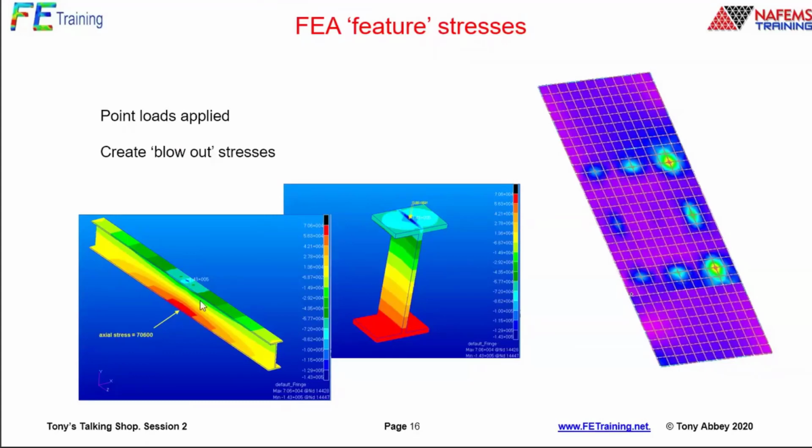This is an I-beam, and we do this in the intro to FEA class, where we just put a load in the middle. And this is a direct axial stress running down in here. And it's building up. This is the actual triangular bending moment distribution building up, and hence the stress builds up in the same way. We expect to get extreme fiber stresses top and bottom the same. They are not at the top here.